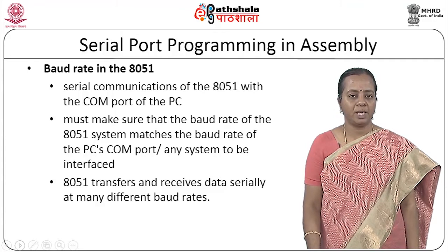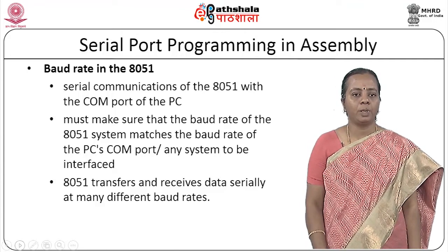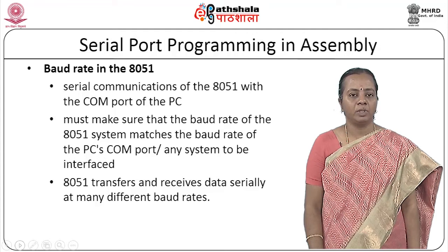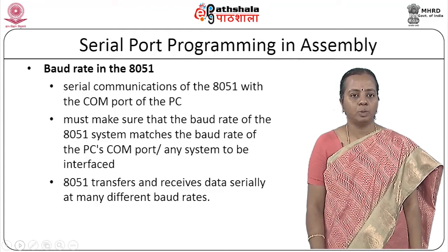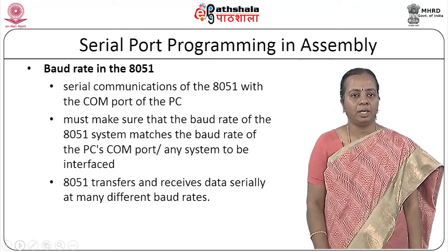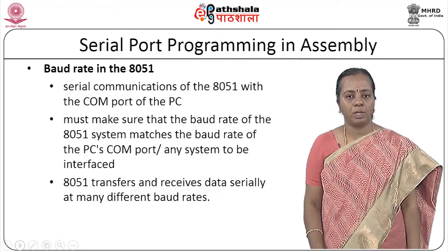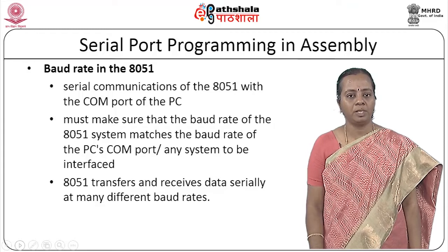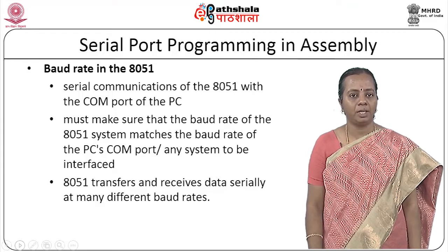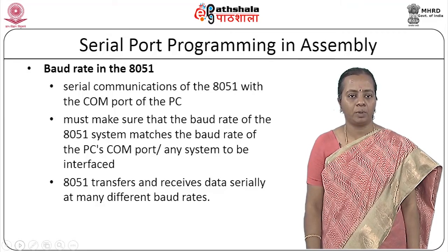So we need to know the speed at which the output device is in a position to receive the data. Then the 8051 will transmit data at that speed only, so that the output device will be able to catch all the data transmitted by the 8051.